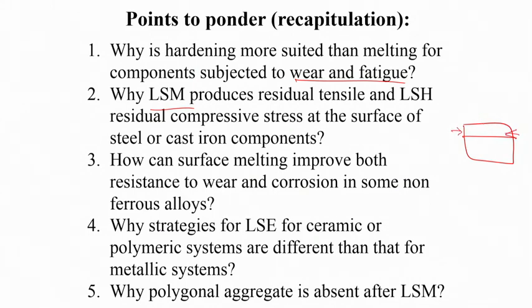In the process, the reaction to that tendency will be residual stress acting away from each other, so tensile in nature. So this kind of situation is not desirable. In other words, if you do only surface melting, this is the kind of scenario that you develop on the surface. But in case of steel, you can avoid this because of the possibility of martensitic transformation.